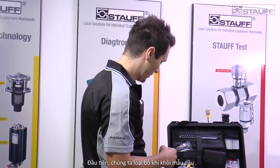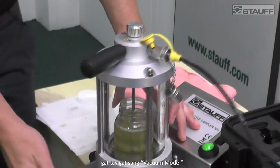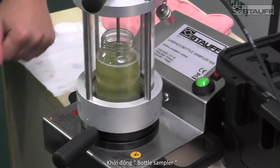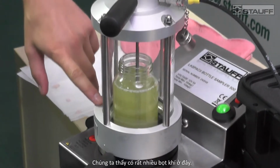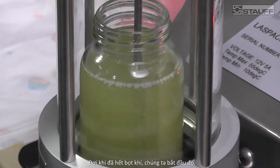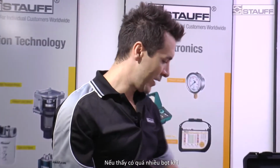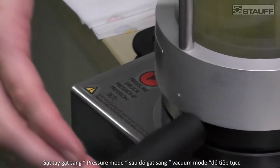First step is to remove all the air out of the sample. So make sure you close the valve, turn the handle to vacuum, turn the bottle sampler on. You can see a lot of bubbles up here. Make sure all the bubbles have disappeared before you commence with the test. If you have too much foam, maybe you have to vent the chamber once, make sure the foam escapes, then start again.